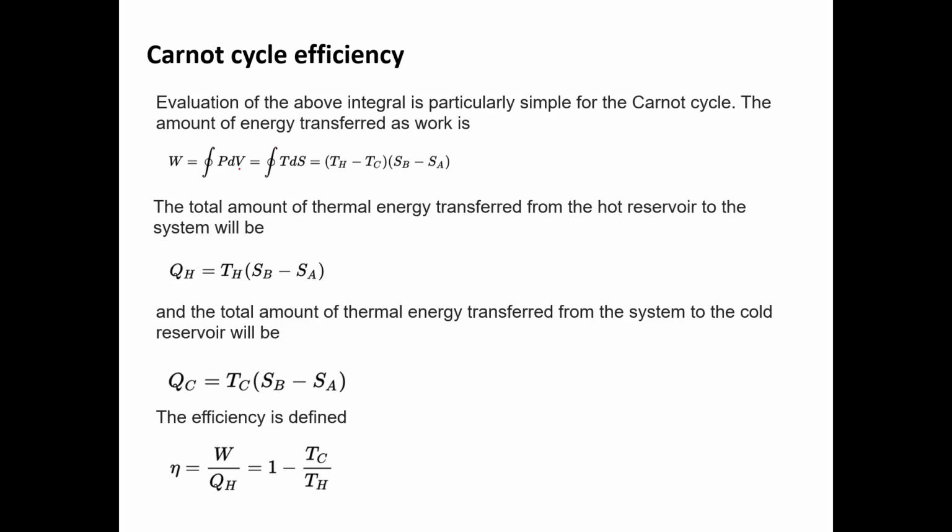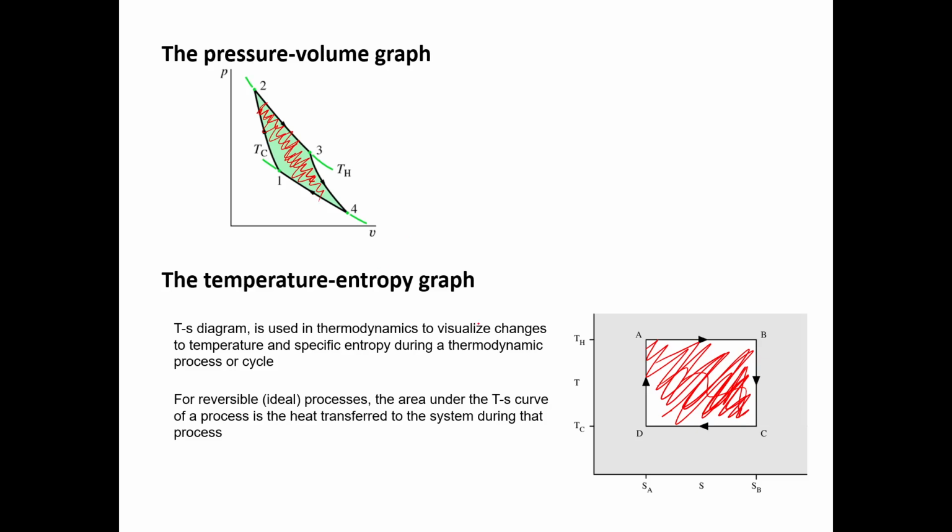The area under the PV diagram, right? Integration basically means the summation of area, right? So the integration of the PV diagram should be equal to the integration of the TS diagram, and also it should be equal to this, right? So this is the total Q that is converted into work. So this is the total work out. Therefore the total work is basically the area ABCD. Therefore we can write W out equal to this area, that means